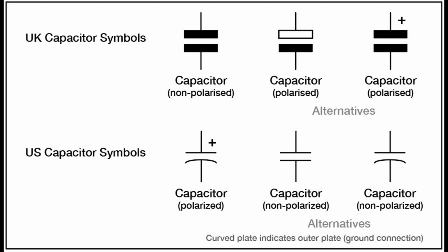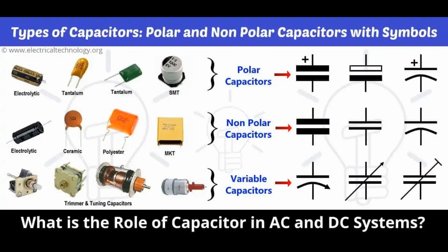Automotive electronics. Electrolytic capacitors are found in various automotive electronic systems, including engine control units, ECUs, infotainment systems, lighting systems, and more. They are used for power supply filtering, voltage regulation, and decoupling purposes in these applications. Industrial electronics. Electrolytic capacitors are used in industrial electronics equipment like motor drives, robotics, control systems, and factory automation. They provide energy storage, stabilize voltage levels, and ensure proper functioning of these systems.